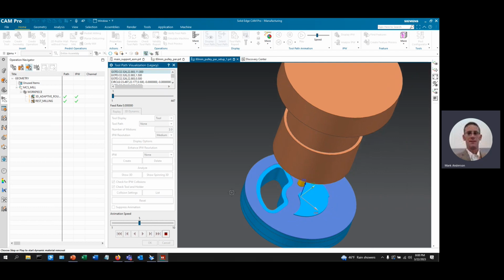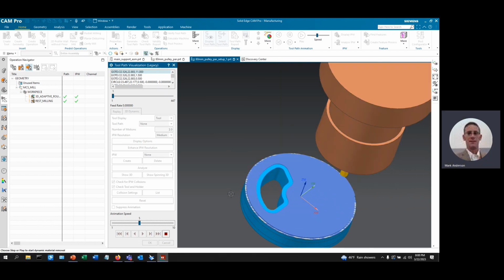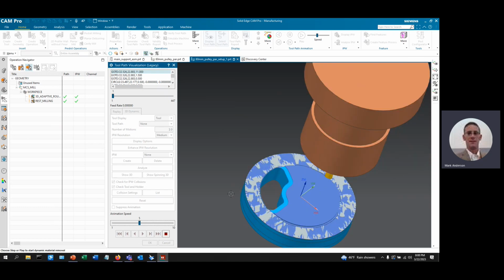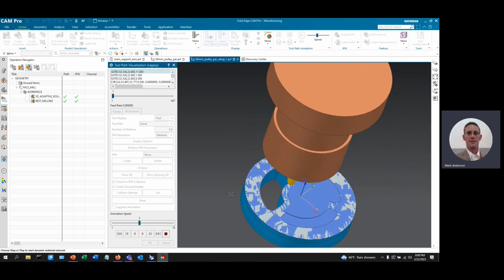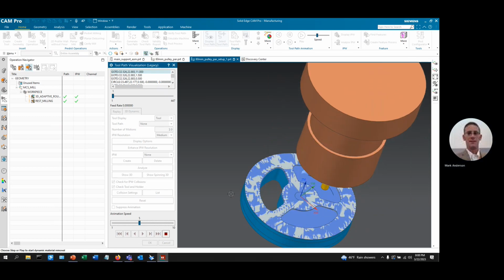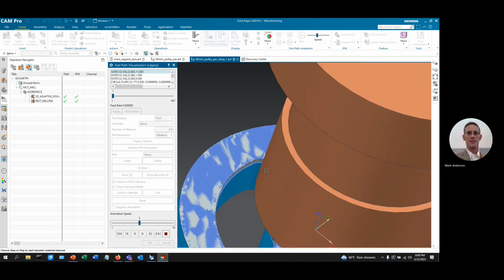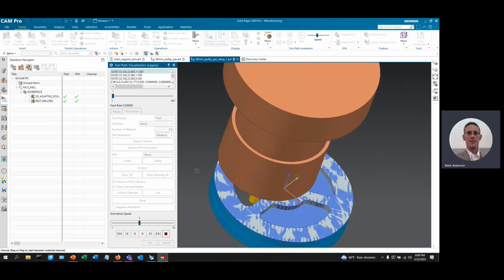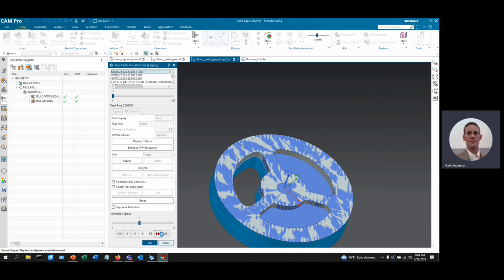So that pocket was already cut out, 1 millimeter left on it. So you'll see how the toolpath will start to shift around that 1 millimeter in that pocket that's been removed. And it navigates all the material left in. You see how it's cutting just material left. It's a very intelligent pattern of toolpath to accurately cut your part.